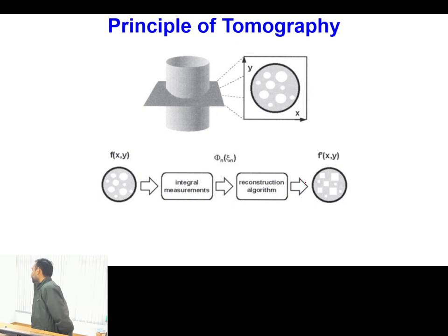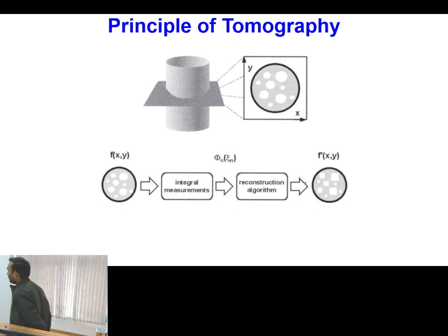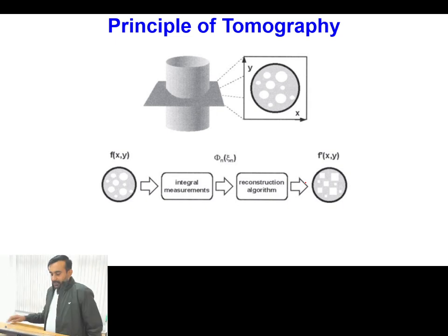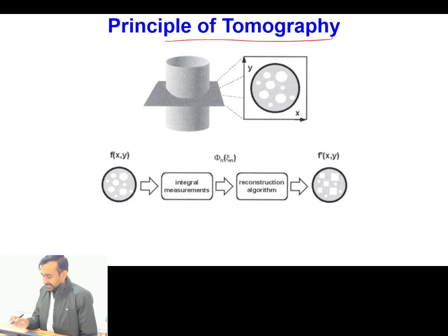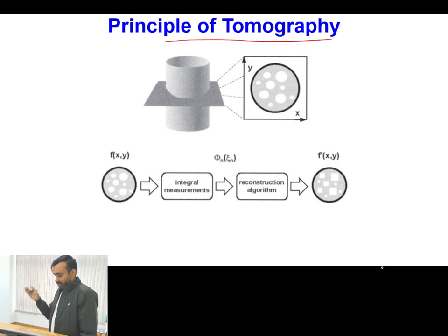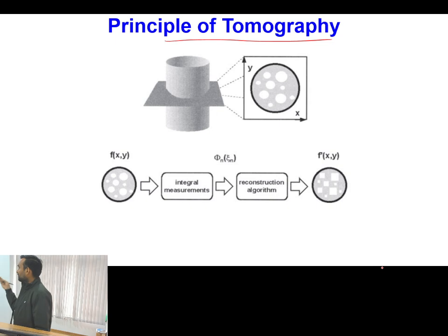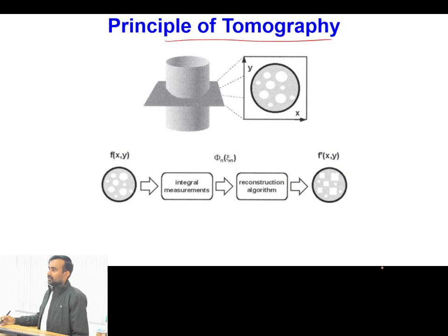Basically, this is giving you a lot of data. So after the data, whatever you have to interpret from that data, you have to do. Okay, so let's understand the general principle of tomography. Of course, tomography can be done in different ways, like radiation attenuation, capacitance based, electrical resistance based. Over here I am giving you the generic principle. So this is the pipe. In this pipe, this is the two-dimensional plane which we have taken, and this plane has two coordinates x and y.